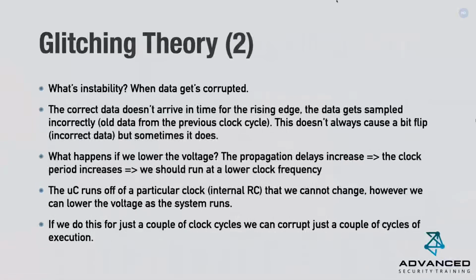And what does that mean, less stable? Well, data is actually going to get corrupted. That means that, for example, instead of reading on a 32-bit bus, let's say, all Fs, it's going to read an E somewhere, or instead of reading all zeros, it's going to read a single bit that's 1. And depending on what the actual comparison is that's happening in the microcontroller firmware, in the boot ROM, that'll affect essentially the security of the device.